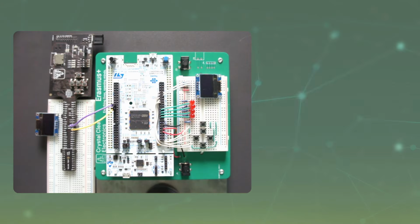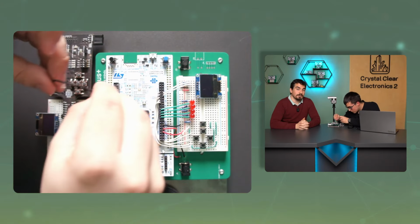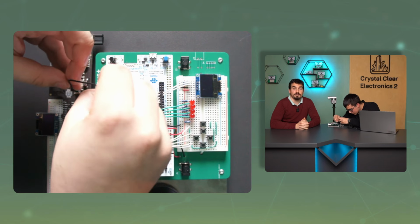The microcontroller decides whether a logic 1 or 0 has just been received based on the voltage at its input. The microcontroller measures this voltage relative to its own ground point, which is GND. For this reason, it's essential here to make the ground point of the two devices common. Find the GND outputs on both devices and connect them with a wire.